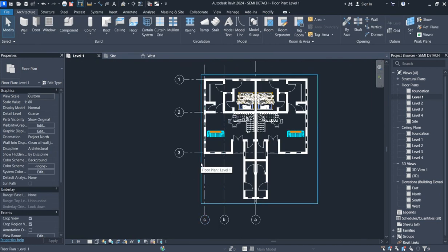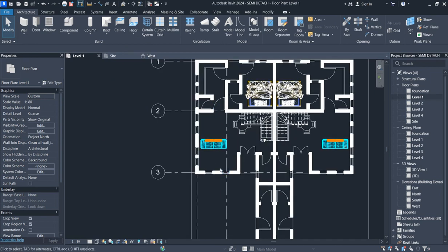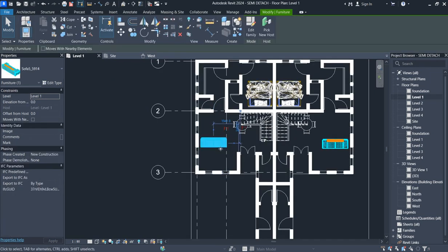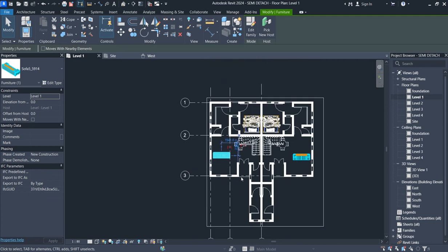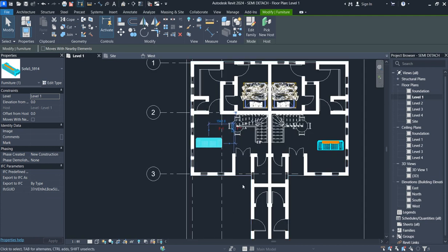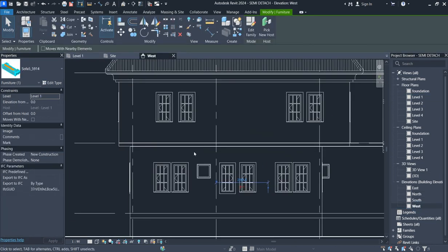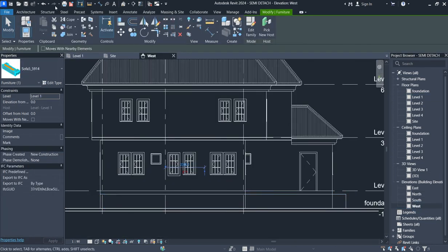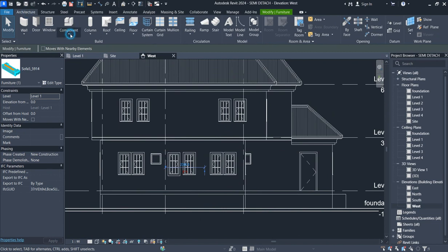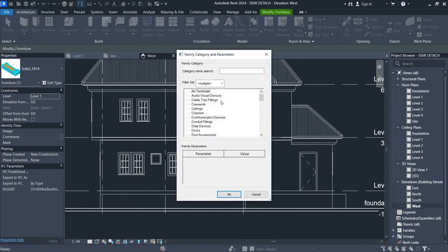So as we have done with this and all this other area of expansion, group it. Now what we want to do is to create a step here. The graphic step, you can decide to draw it here, but importantly you still need to create a step. So you go to west elevation. At the west elevation, you start by calling component, model in place.